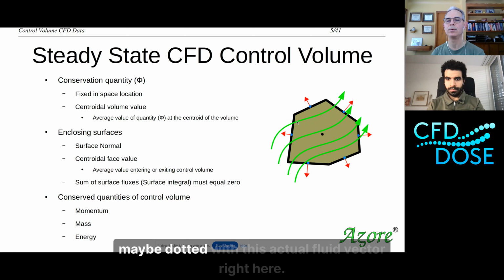We know a lot of these things. Typically we know a lot about our geometry, and we know a lot about the density of our fluid, but the velocity is often what we're really interested in. Based on conservation of mass, we can figure out perhaps what the velocity is at this location, or perhaps at this location. But with our CFD tools, we want to know a little more information about what's inside our box. What perhaps might be the velocity at this location.